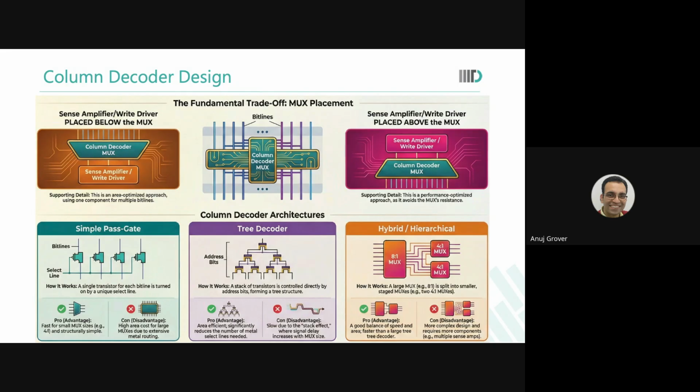When we are talking about I/O, we are saying that finally the implementation of connecting my bit line to my sense amplifier or write driver to my bit line, that is where the mux operation is happening. Just the control signals are being generated somewhere else. So for us in this course, or for the terminology that we will use over here, we will say column decoding and mux are same. Now to generate those control signals, you need some logic. That logic you may decide to put inside your control block because that is common to all the IOs. Are you with me?